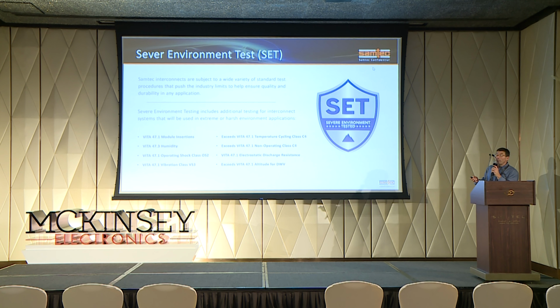And then severe environment test. So we've had what we call an extended life product, ELP, for many years, where we put products through extended testing for nitrous acid, gas, etc., and shock and vibe. So we added the SCT, which is closely mapped to VITA 47 and VITA 42 testing, to a higher class of shock and vibe.